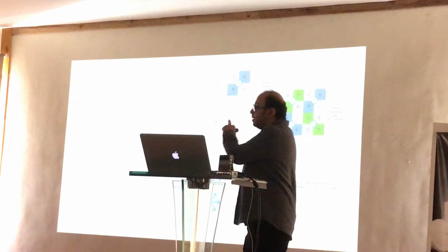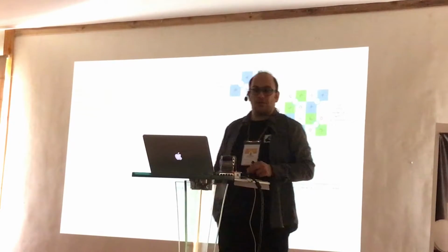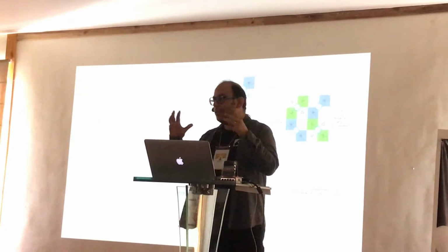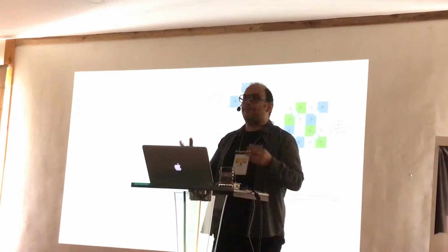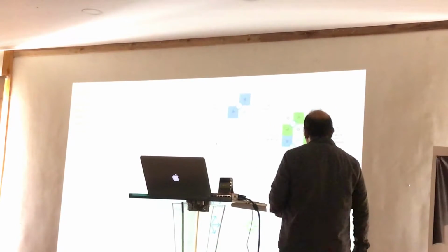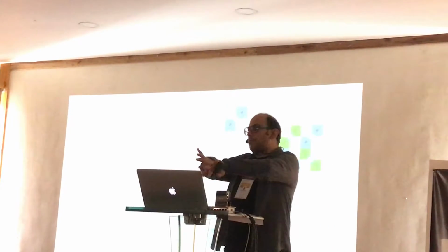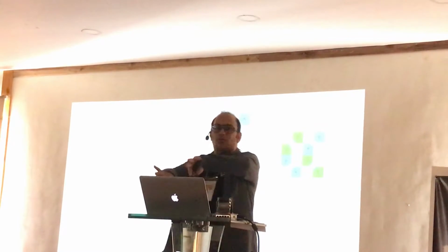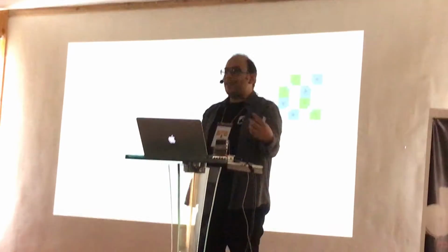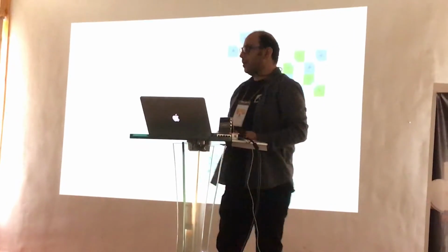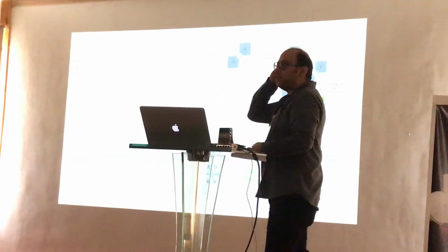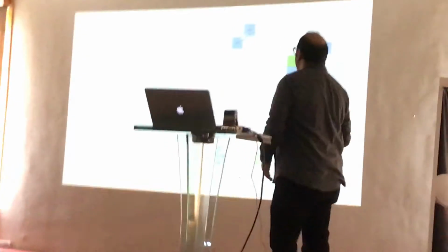But Cambium was the first company to synchronize access points. The main idea is just to reduce your self-interference. Because the problem is, when you have two back-to-back access points, one of them may transmit while the other one may receive, so they interfere with each other. GPS synchronization can reduce this interference.